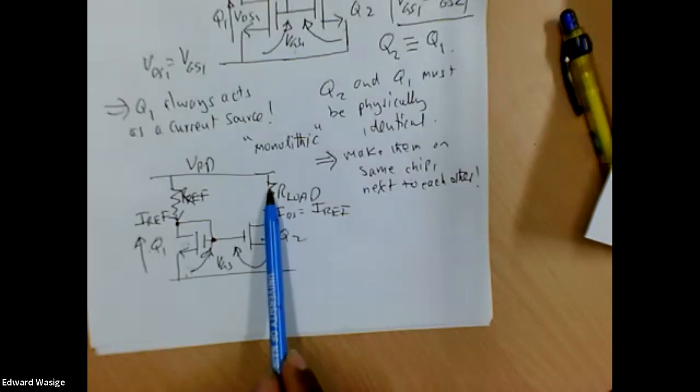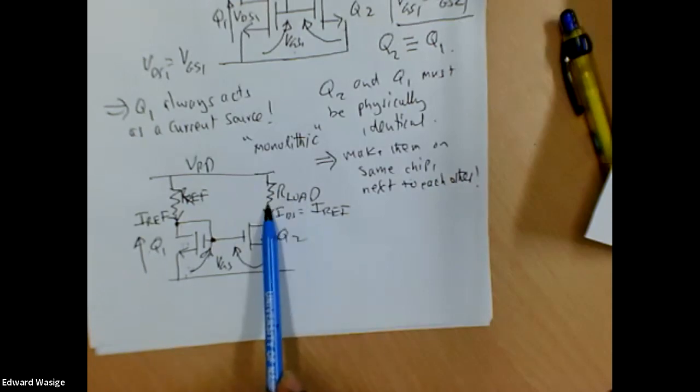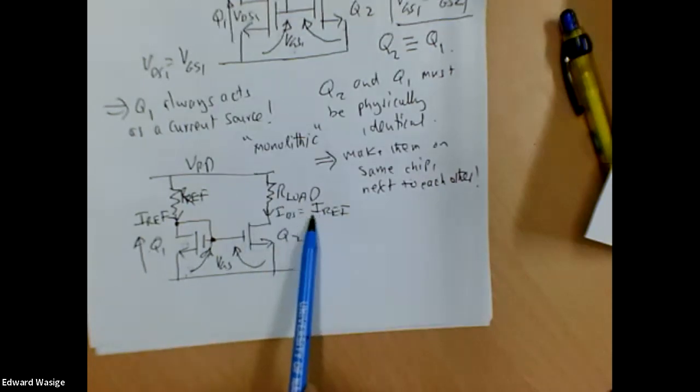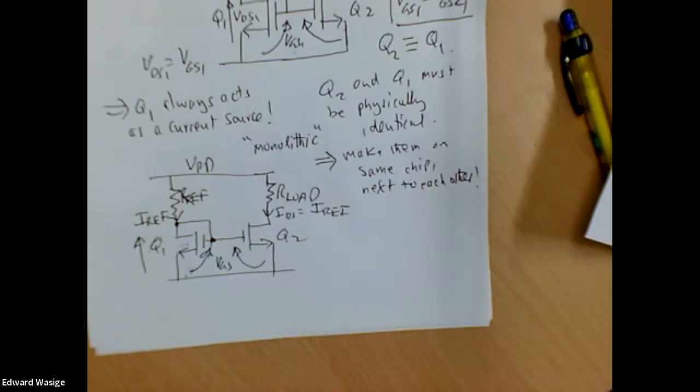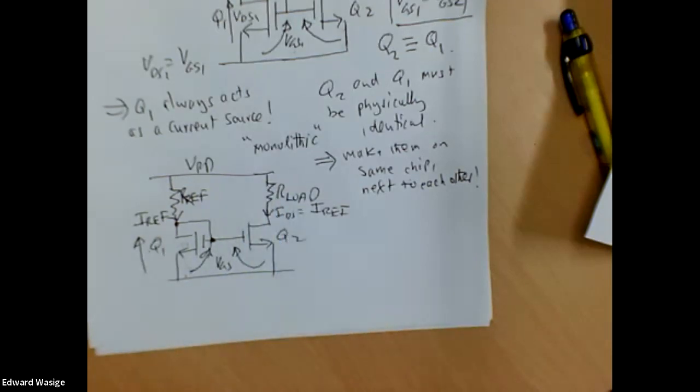So the load, if that's a short circuit, it works. If it's an open circuit, the whole of this breaks down. But for any other load resistance, the current will always be the same as the reference current IREF. It doesn't matter the value of the load we put there. And try that in the simulation. The theoretical explanation might not be very clear, but try that in the simulations. If D and G is connected, it can also be equal to IREF.